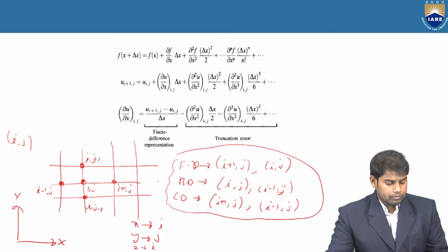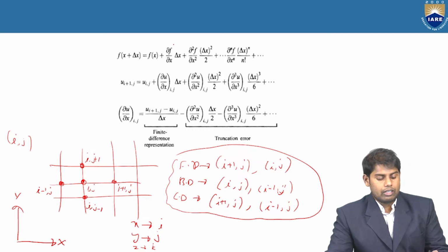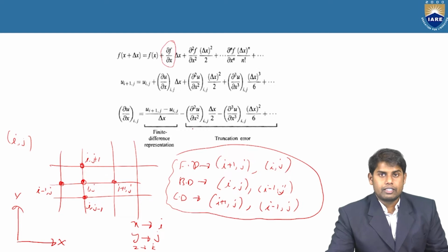Okay, so basically these things are important while calculating the fluid flow properties at the particular grid point. When we are iterating, we will give the index notation and solve it. That's why we are giving the index notation for the finite difference methods. And how we solve is, we will discretize, or change, this partial derivative into a discretized form, arrange it in a set of algebraic equations, and invert it.